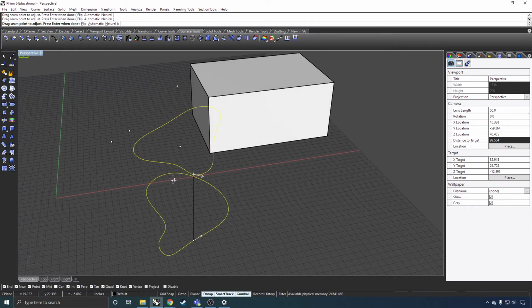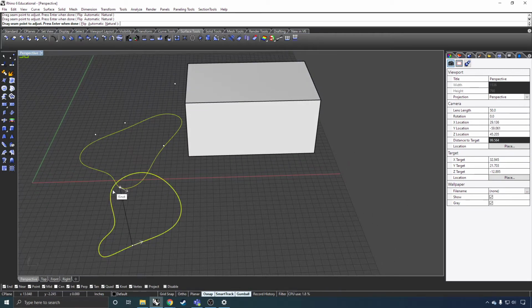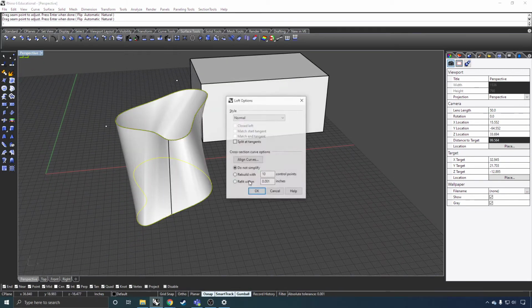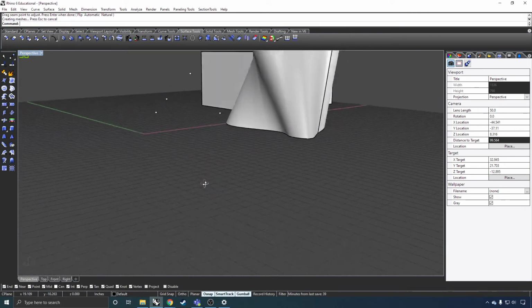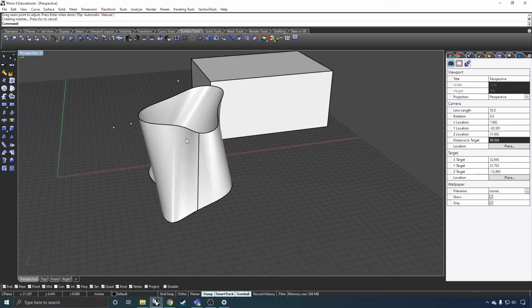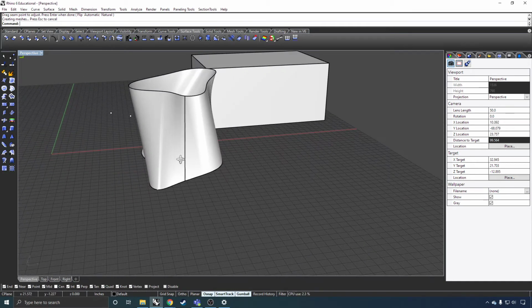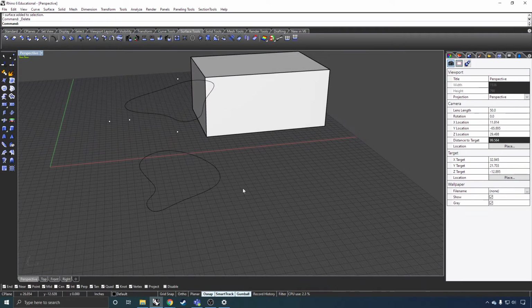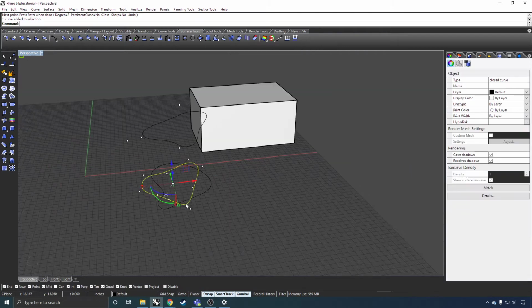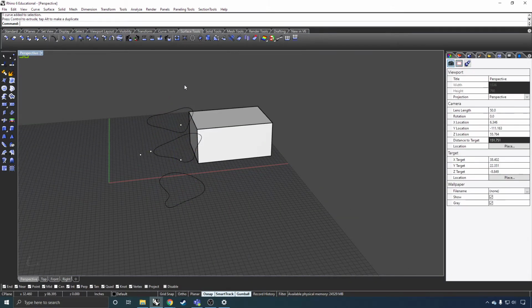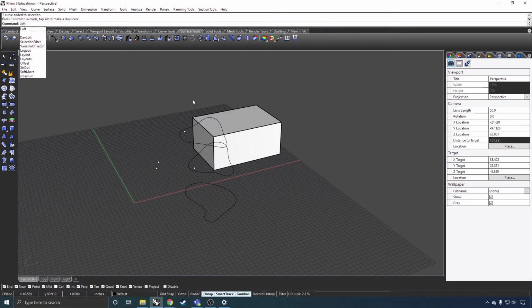You have to click on the arrow to get it to go the right direction. But now these are both going the right direction. If I hit enter, it's going to give you a couple of options here. Feel free to play around with those, but you'll see it's transformed the bottom thing to this thing. It's often doing this with mostly straight components. If you make a third one, and this is something that Revit has a very hard time doing, and then loft them.